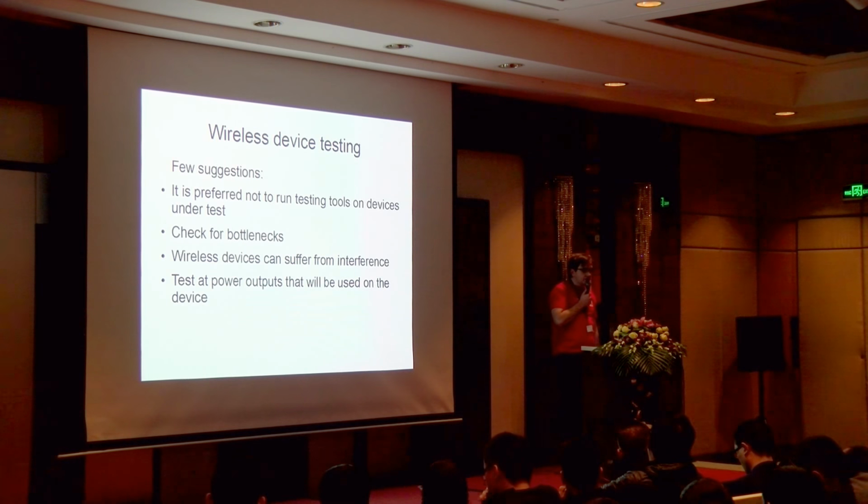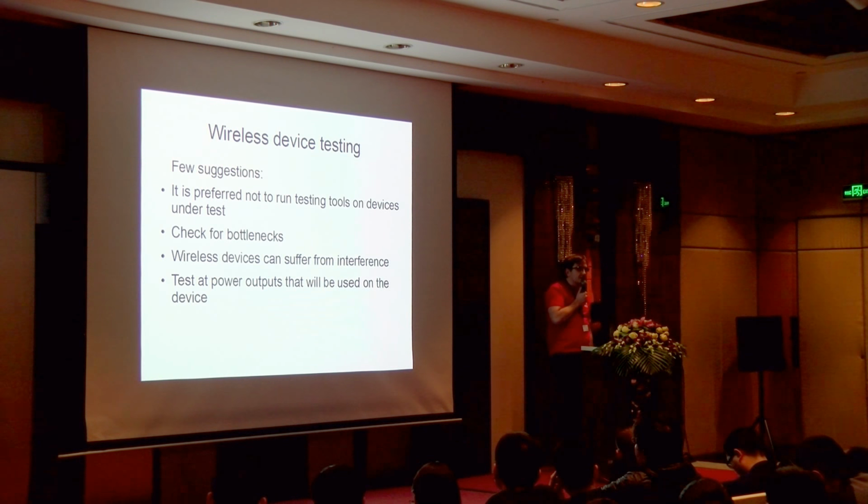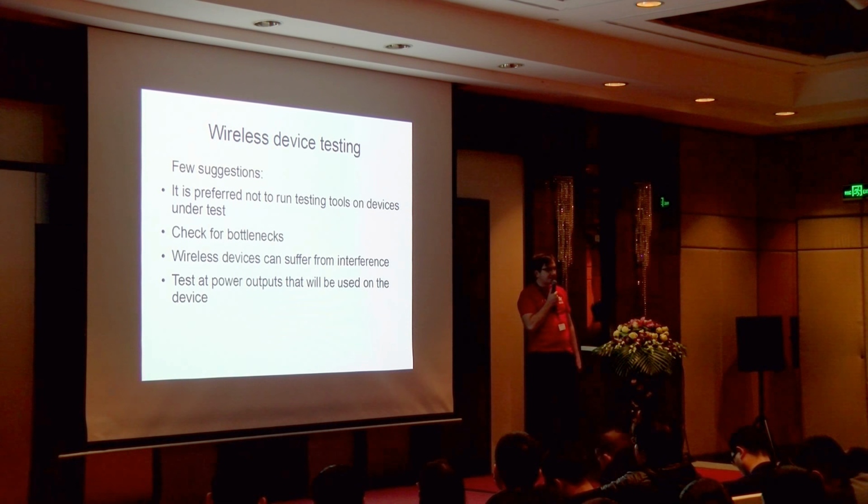Always check for bottlenecks, because sometimes it's the CPU because of a testing tool running on board, or the Ethernet interface, for example.